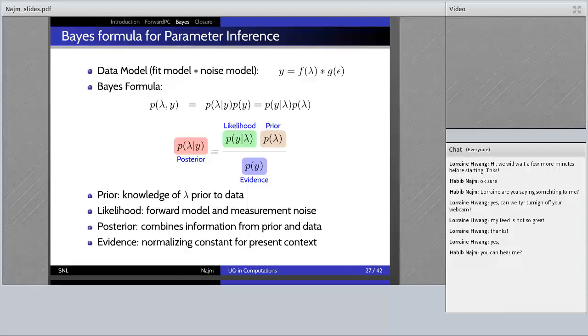There's the Smagorinsky constant, which defines the character of the subgrid model within this LES computation, as well as the turbulent Prandtl and Schmidt numbers. These are the uncertain parameters, and we use second order Polynomial Chaos. We evaluate the model at 25 points only, and we have the predicted uncertainty in the output. So this is how it's used typically in any type of model.